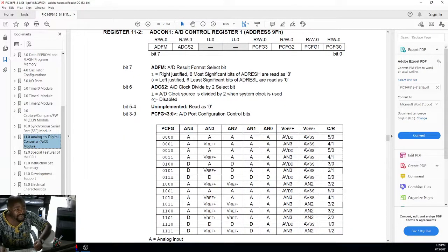So disable that. So 0, 0, bits 5 and 4 are on default 0, meaning the 4 upper bits are 0, 0, 0, 0. That makes in hexadecimal a 0. And now this one makes in hexadecimal either a 6 or a 7. So moving 0, 6 or 0, 7 in hexadecimal to ADCON1 will configure your port A pins as digital pins.